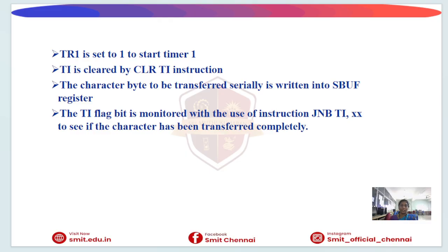Next, the data byte or character to be transmitted is loaded into the SBUF register. This SBUF register is the serial buffer register used for both transmission and reception. After loading data into SBUF, the microcontroller automatically starts transmitting the data serially through the transmission pin. The program continuously checks the TI flag. When the transmit interrupt flag becomes 1, the transmission is completed. If it is 0, the previous transmission is not completed, and we wait for the process to be completed.